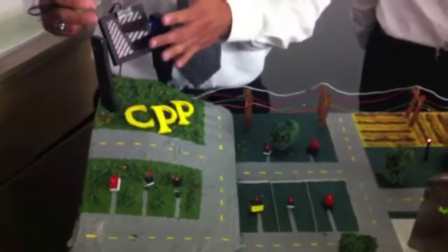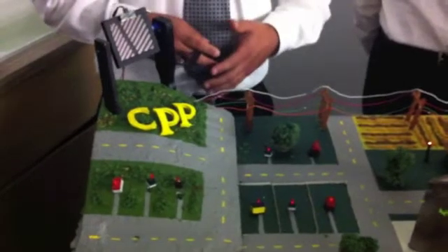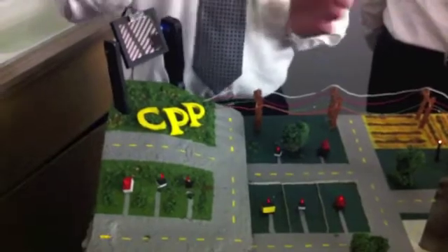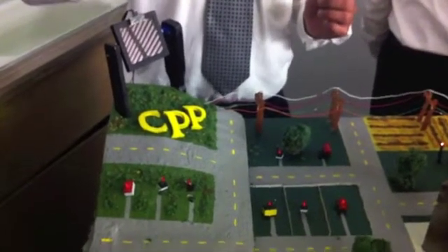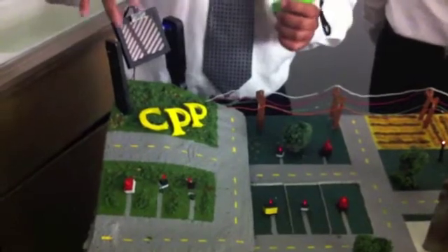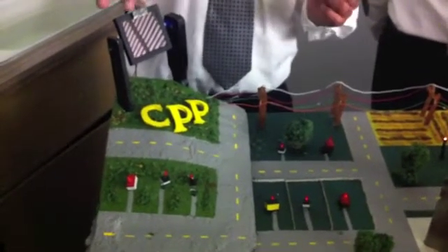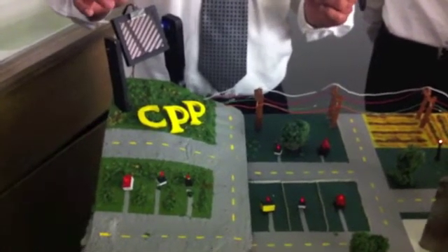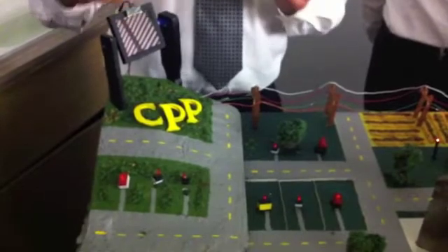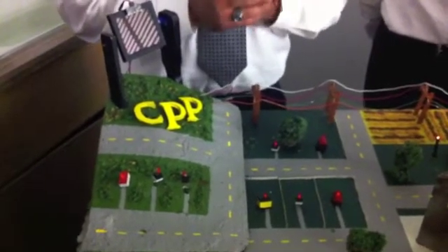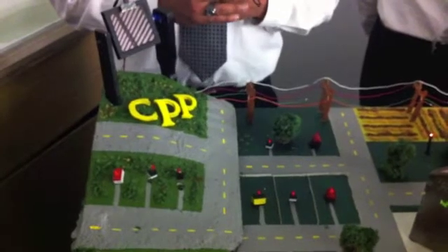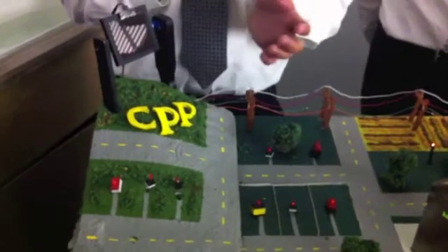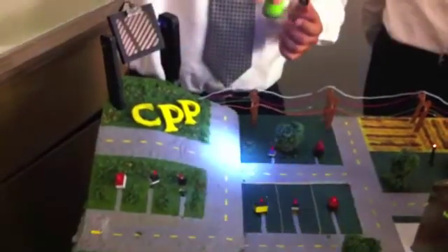So we have our solar panel here, which is going to feed to a battery, and the battery is powering our LEDs. So right now we're simulating nighttime, and I will be simulating daytime using this flashlight. The way it works is we have our main solar panel that's going to be charging through the sun, and then we have a smaller solar panel that works as a solar cell sensor to do the logic with the voltage and send it to our PIC. But I'm not using the PIC, we are using the MSP430 as our microcontroller to control the logic of the servo, and hence going to move the servo back and forth. And I will simulate the sunset.